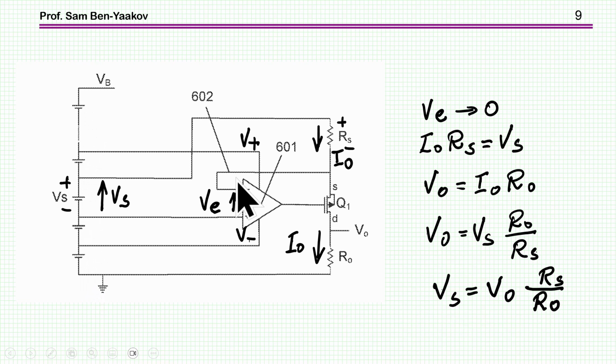Okay, this is an amplifier which is in a closed loop, and then we have a p-channel transistor, which produces a current that is fed toward ground here. Now without feedback, the whole input voltage, V sub S, will be imposed on the input terminals of the operational amplifier. This will cause the voltage to go down.